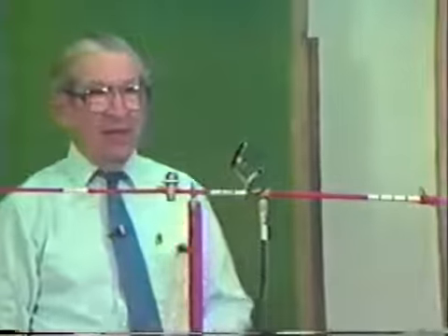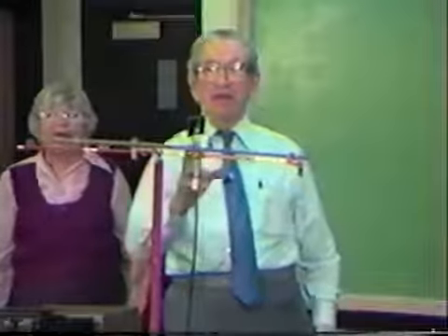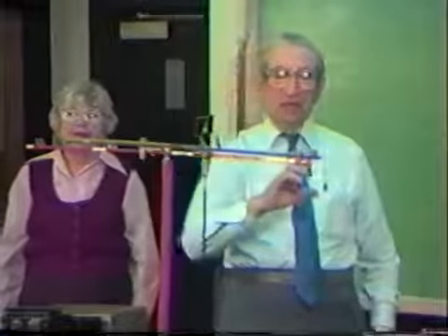Can you all see that? Now let's see something else. Don't forget, this lamp is bridged across an inch or 2 inches of the aluminum itself. On ordinary thinking, that would be a short circuit. But when we're dealing with radio frequencies, there's a skin effect that takes place, and all of the current and all of the voltage is on the skin of this element. Not through the element, but on the skin of the element.